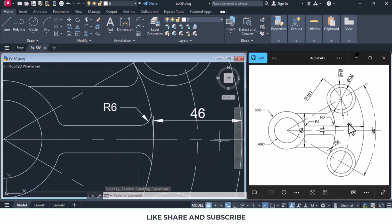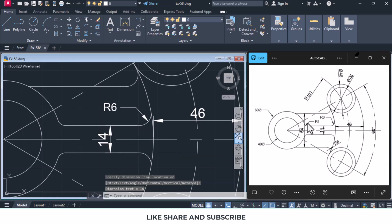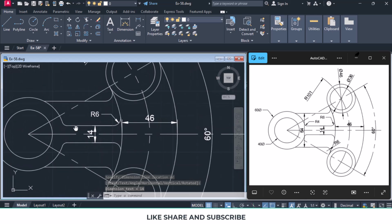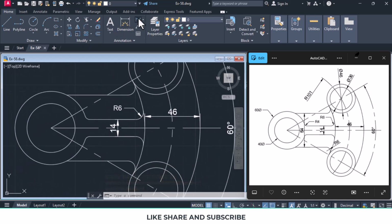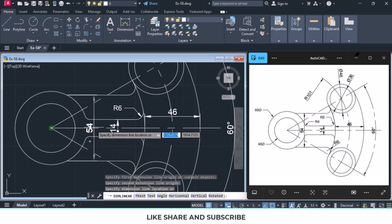Then we want this 14 units. So linear dimensioning, we click over here, turn the snap on. So here and specify 14 units. And then this dimensioning we want. So again linear dimensioning from here to here and specify where you want.